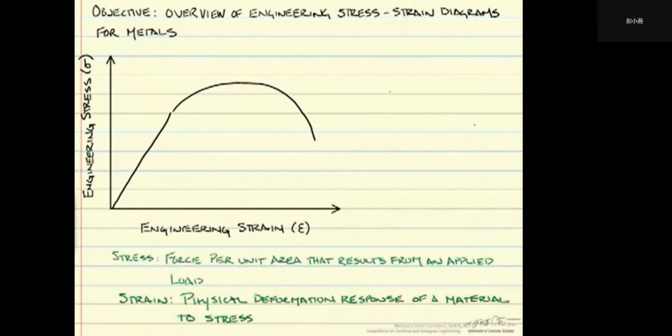When a test specimen is first placed in a tension testing machine, the force is increased and the strain is proportionally increased. If we look on our stress-strain diagram, this is the linear portion of our graph. If you were to release the specimen in this region, the specimen would return to its original shape, so no deformation has taken place. If we think about the specimen at the micro level, the bonds are stretching. This is considered the elastic region of the stress-strain diagram. The slope of the line in the elastic region is the modulus of elasticity, also known as the material stiffness.